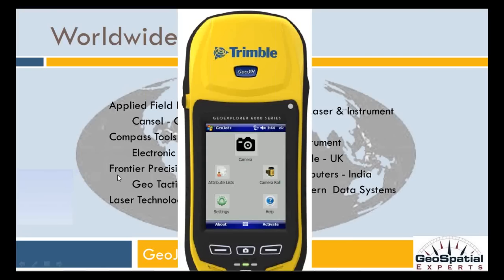And another question about accuracy, someone's asking about post-processing the Trimble data, and could we possibly use that? Right now we use the live feed from the Trimble units in GeoJot running on the app, on the device, but it is possible to collect that post-processing data, run it through Pathfinder Office, and then use the geotag function in our Windows desktop core software to basically re-geotag the photos with the high accuracy that you can get from the XH data. So the data you take out in the field would be the live accuracy GPS, but you could then re-tag them with the higher accuracy XH data very easily back in the office.